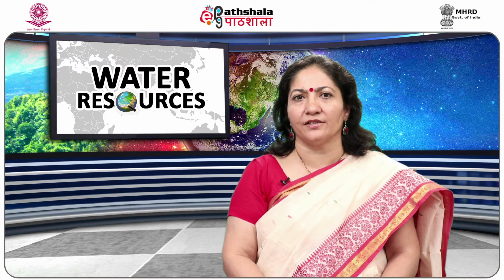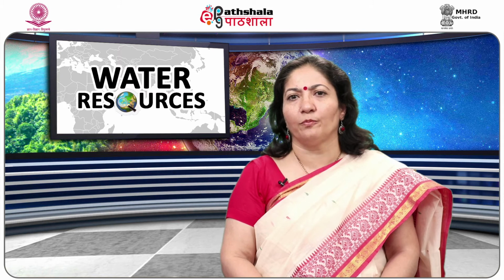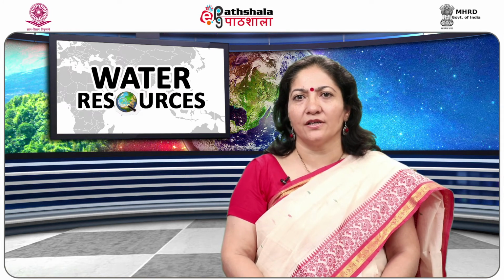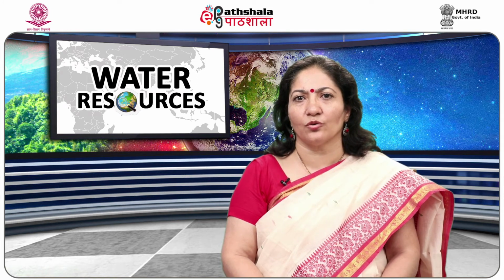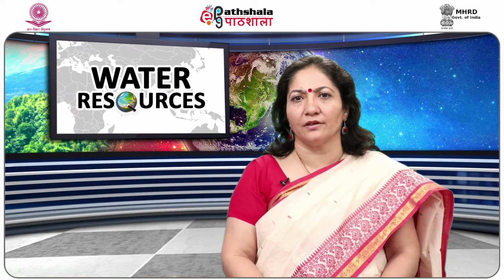Second, permeability. While porosity tells us how much water rock or soil can retain, permeability is a measure of the capability of rock to transmit water through its pore spaces. It is the property of the soil to allow water to pass through the gaps between them. Since voids are present in all soils, even in the most stiff soil, clay, they all are permeable. It is a slow process, on average being a few centimeters per day.